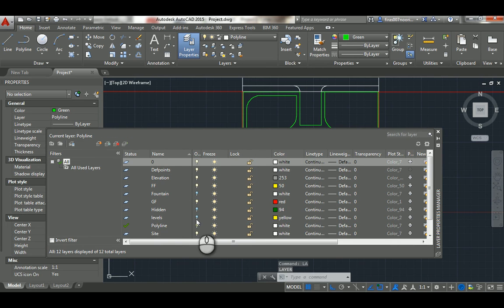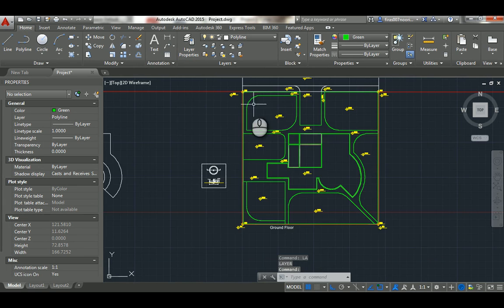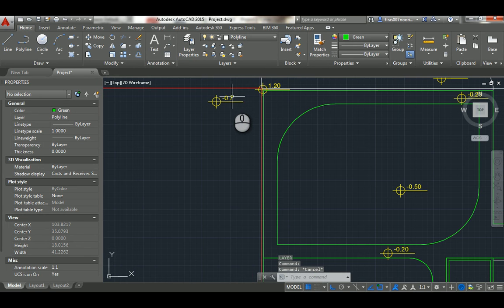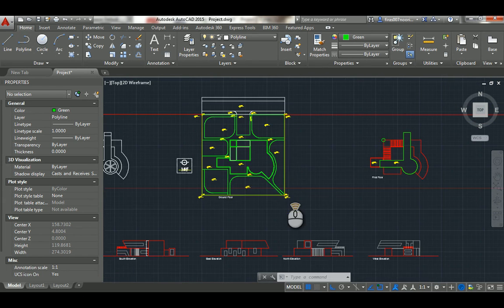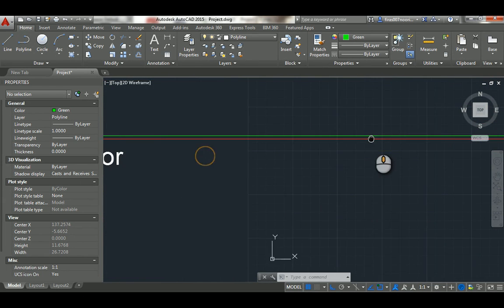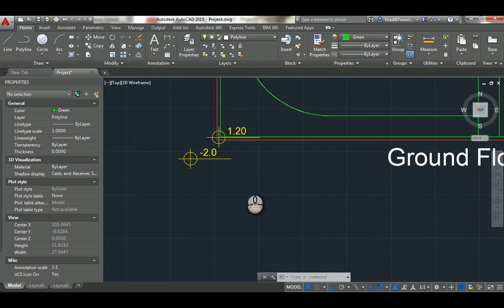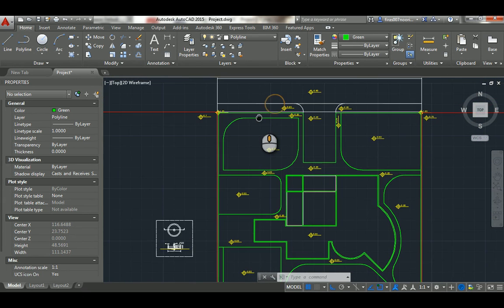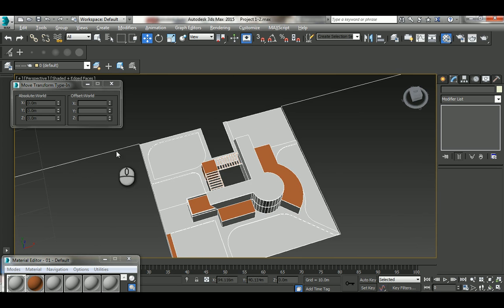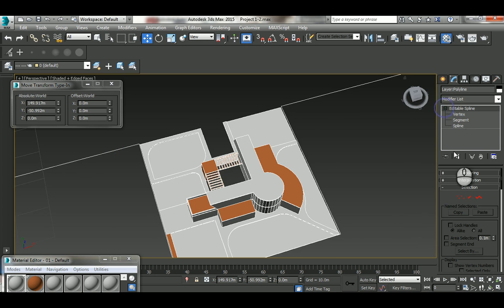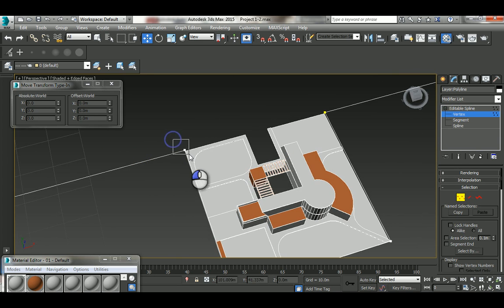and from the layer I'm going to turn on the levels, and I'm going to see that the points of the nearby lands, or neighbor lands, are -0.7 near the street, while this one is -1 and here -2. In order to do that, it's a very easy trick. I'm going to select this and then open the vertex and select this point, and then with the control key select this one and give it a -0.7.